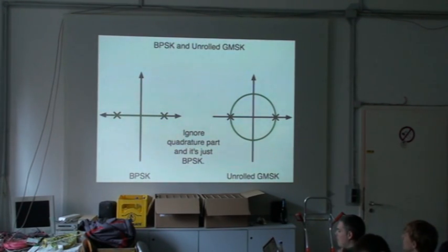It's just that simple. And when we construct the outgoing signal, we do just the opposite. We construct a BPSK signal, we apply the complex channel filter, and then we frequency shift it. If you read what the spec says about how to build the GMSK signal, there are phase modulators and all kinds of crazy stuff in there. You don't need any of that. It's a convolution and a frequency shift.